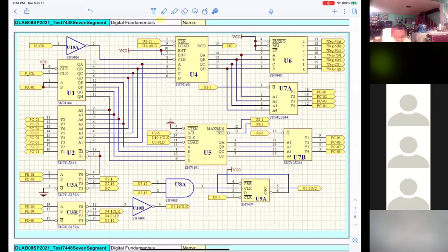You want pin 3 to be 1. Okay? You want a logic 1 here. You use your meter to measure. You get 0. Okay? Then now you have to go to the input. That means go here. Right. Measure pin 15.